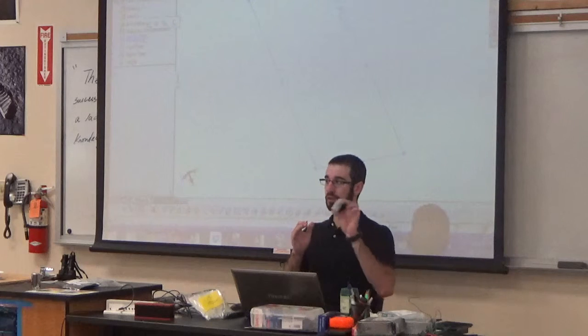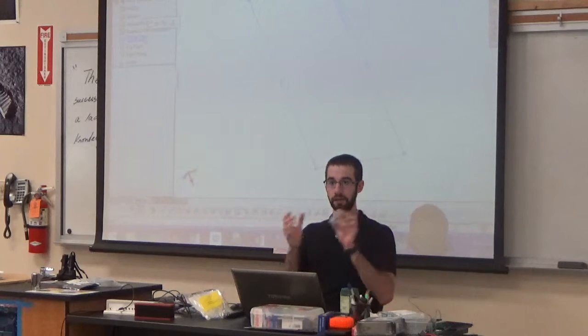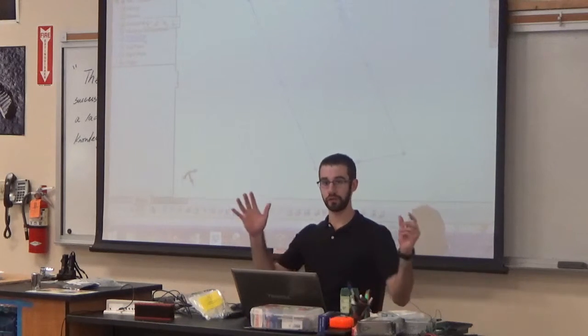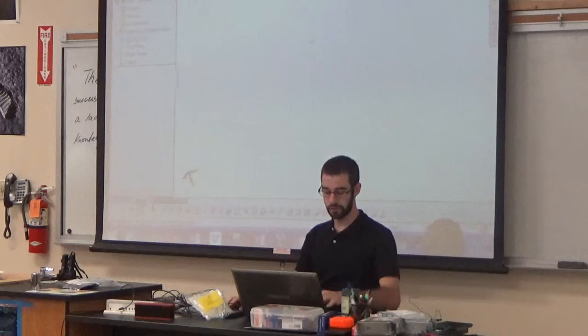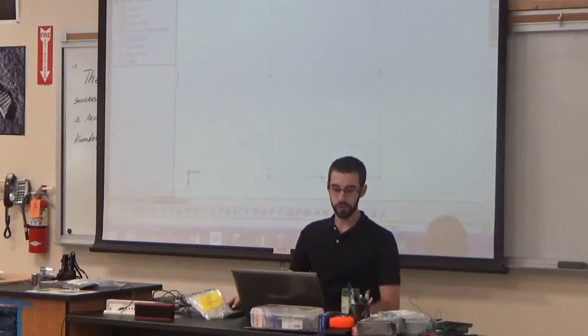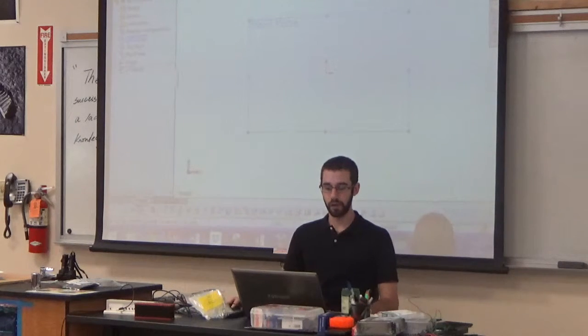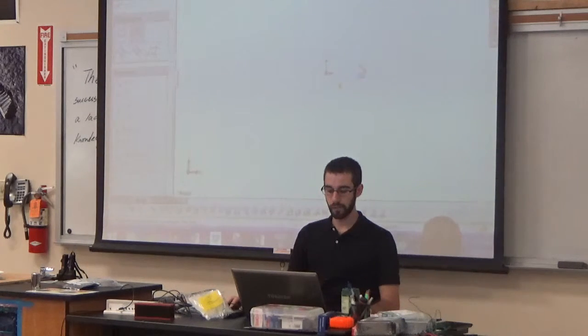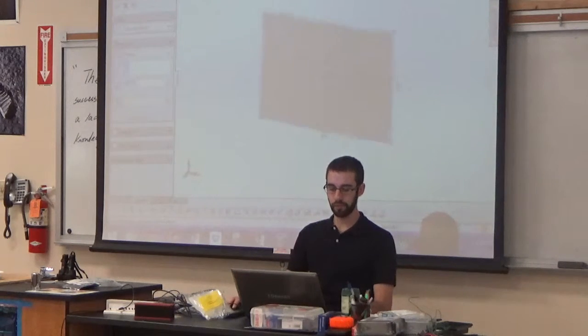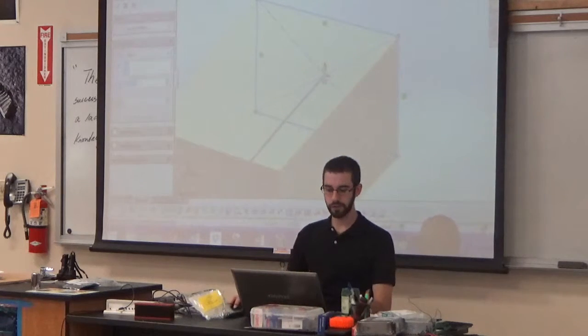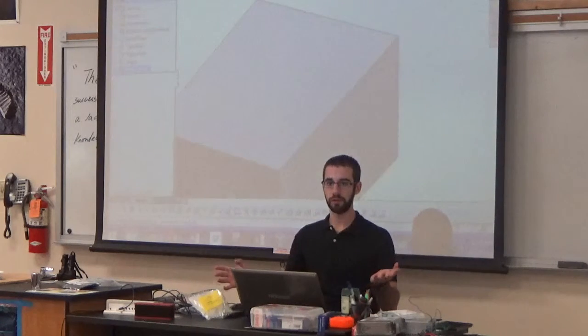if I look at the 2D shape of it, it's a square. And the idea with CAD is you extrude shapes or you can cut shapes. For example, if I wanted to make a box, I would first do my 2D sketch. Typically you dimension these too. I'm not going to do that, just to show you. And then you can extrude it. So let's extrude 5 inches. Now I have a box.